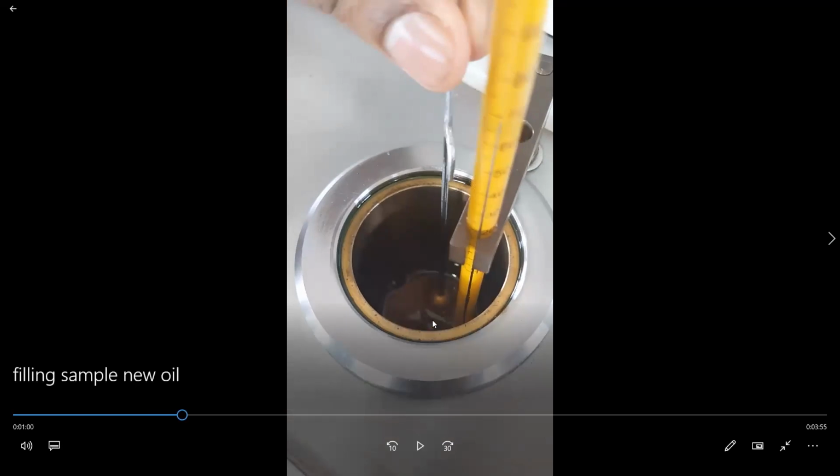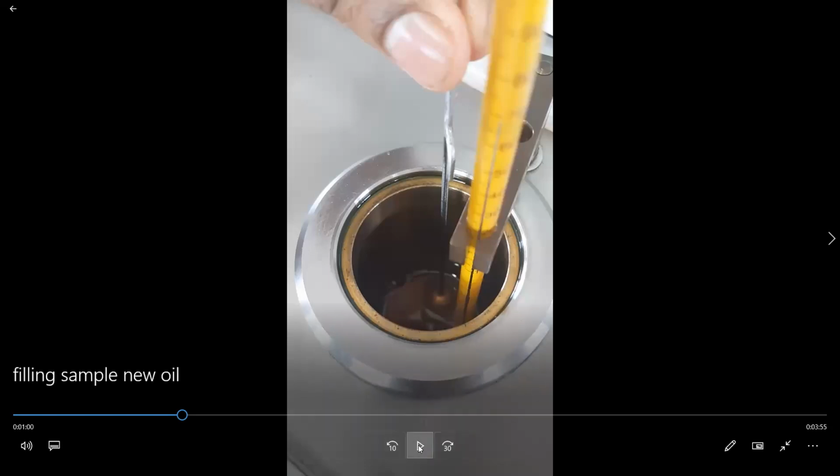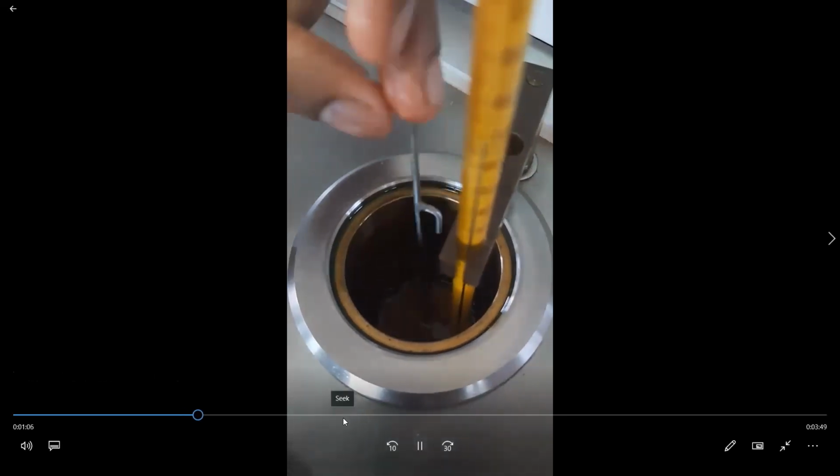You can see that orifice, that small hole, is at the bottom of the spherical shape, right? When we put this ball in, it blocks the flow of the oil, right? Then when we start to collect, we have to hook up this ball valve. Then we can start to collect. At the same time as we lift this ball valve, we have to press the button of the stopwatch, right? So while we are heating, we have to block this orifice using this ball valve.